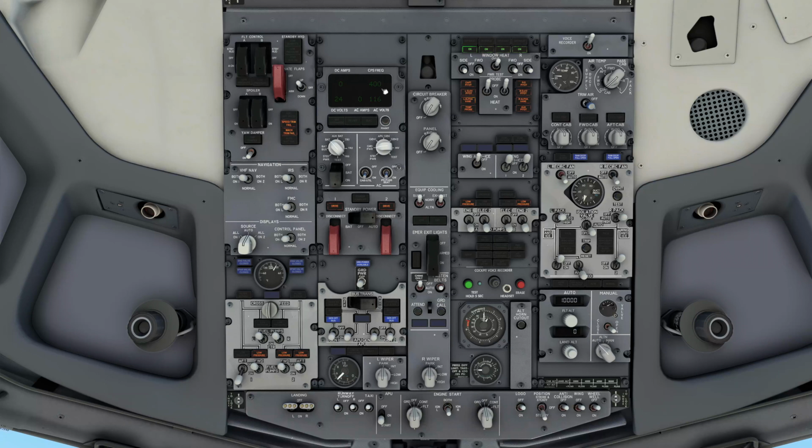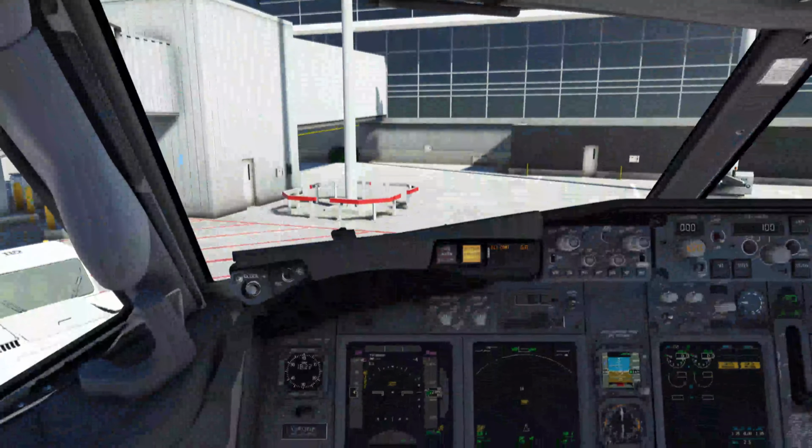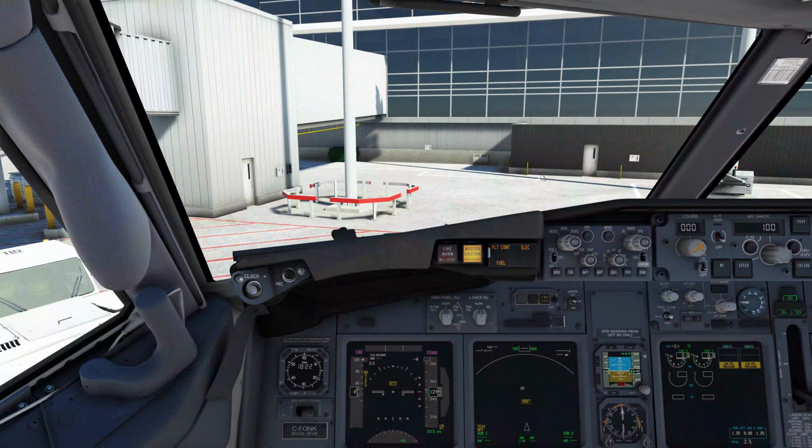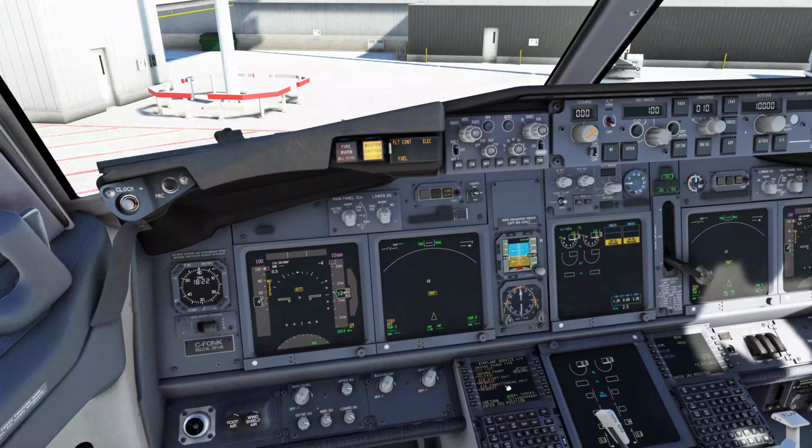If we look up here on our power panel, that's showing our ground power, but we can also turn it over to the APU, and we can see the power that's coming off the APU. So we'll come back down here, see the aircraft. She's powered up, the navigation lights are all on. So these are all up, and that is fine. So I'm going to do some quick loading. You can do the passengers if you want, however you want to do it. For the sake of this video, we're just going to do a quick load for everything, so we get them loaded in.